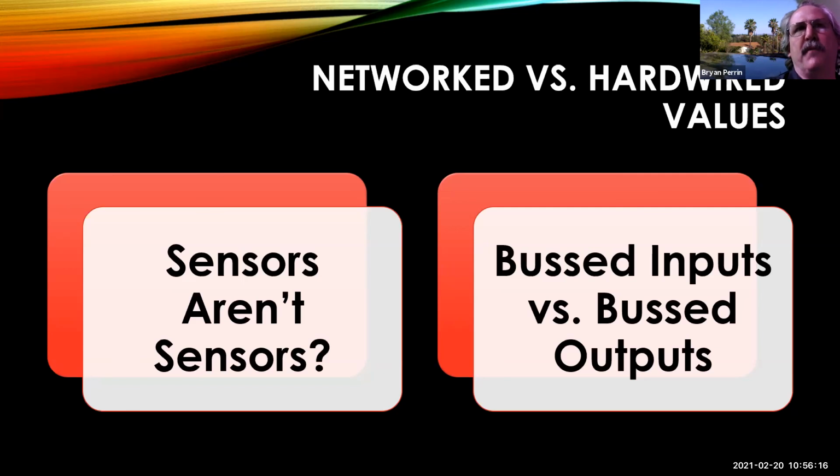If I'm on a GM and I want air conditioning, my climate control module is going to ask the engine control module to turn on the AC compressor, right? So my bidirectional control for the AC compressor is actually in my PCM, but all my requests and everything else are in HVAC.